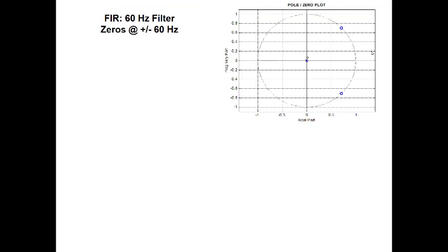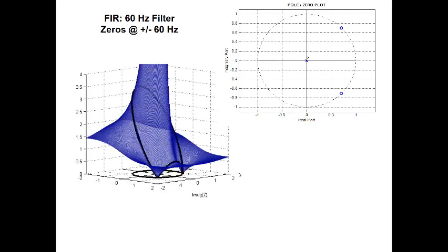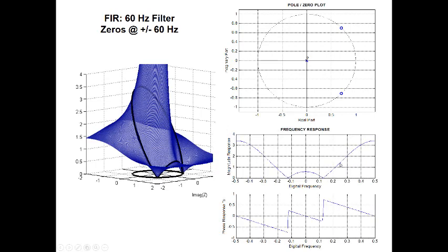So let's run it through our MATLAB analysis. We do a little freqz on it. We run it through the rubber sheet analogy, and we see that, sure enough, I've pulled down the rubber sheet where I wanted to, pulled it down to 0. It's given me a frequency response minimum in zeros right at the frequencies I want.